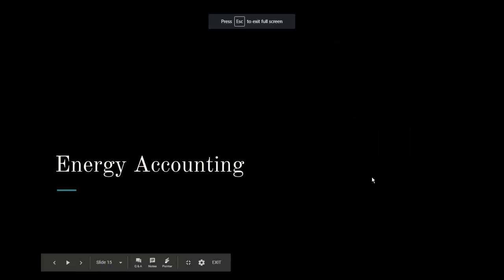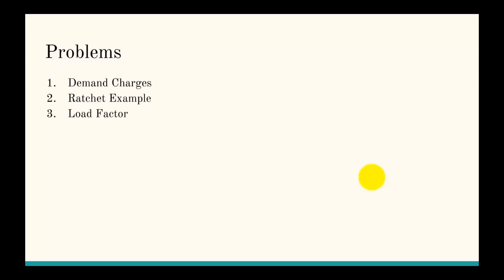For this video, we're going to cover energy accounting CEM questions. So let's get started. We're going to cover a demand charge problem, a ratchet example, and load factor.